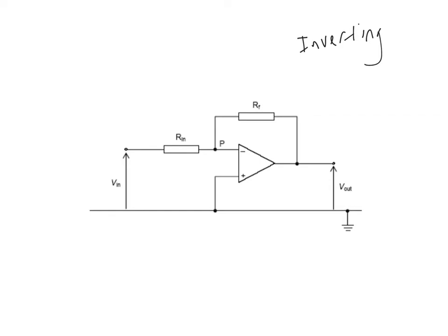So you will see that this is different from a comparator. A comparator won't have this, right? It's called open loop because whatever the input, you get the output, end of story. But now, this inverting amplifier has negative feedback, so it brings the output back here. So this is one difference between a comparator and an inverting amplifier. Another difference is that in an inverting amplifier, the non-inverting input is always earthed. So how does this reduce your gain? Okay, I'll give an example.